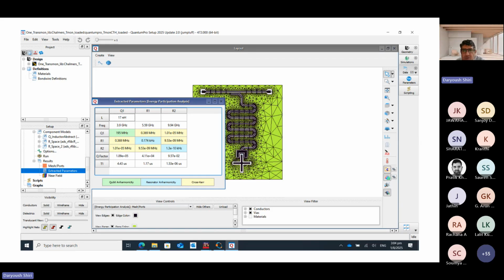For example, if you are a CMOS chip designer and you are given a new technology, let's say FinFET technology, 7 nanometer channel length, you have to have a bunch of simulations in Cadence, simulate your transistor bias, calculate the IV characteristic, transconductance versus, for example, width of the transistor versus gate length of the transistor, etc. Those plots are basically your design library, and from that you can start to design a bias and amplifier, etc. So here also you have to have that kind of attitude.